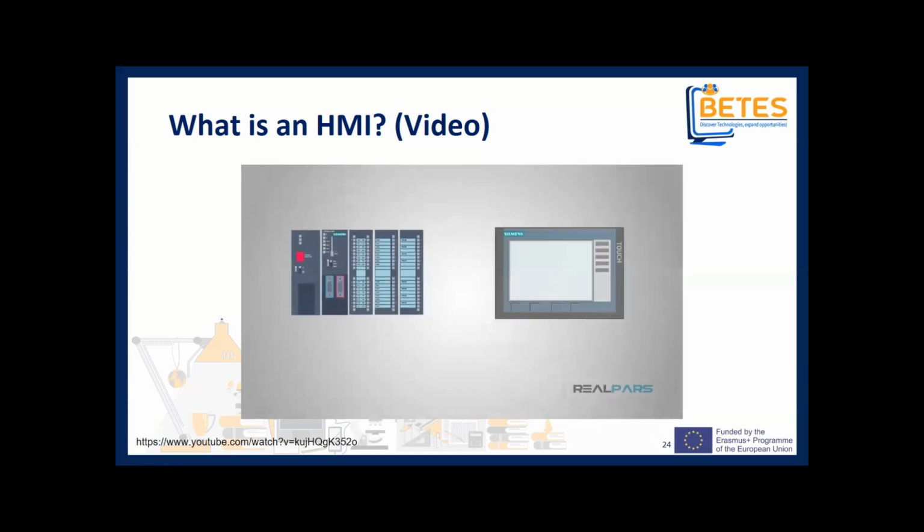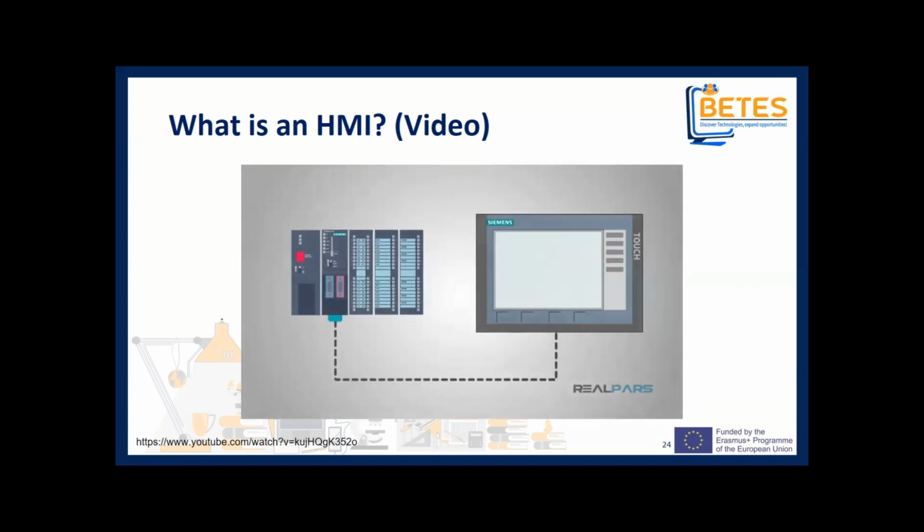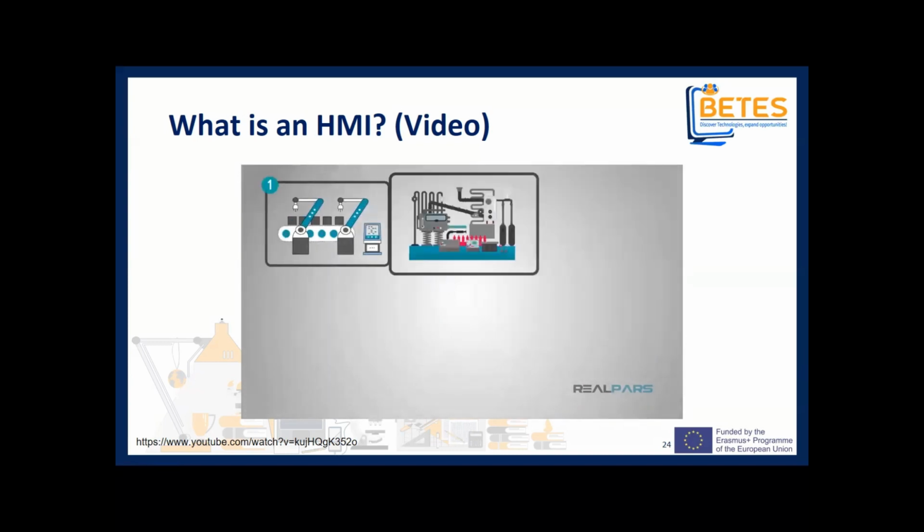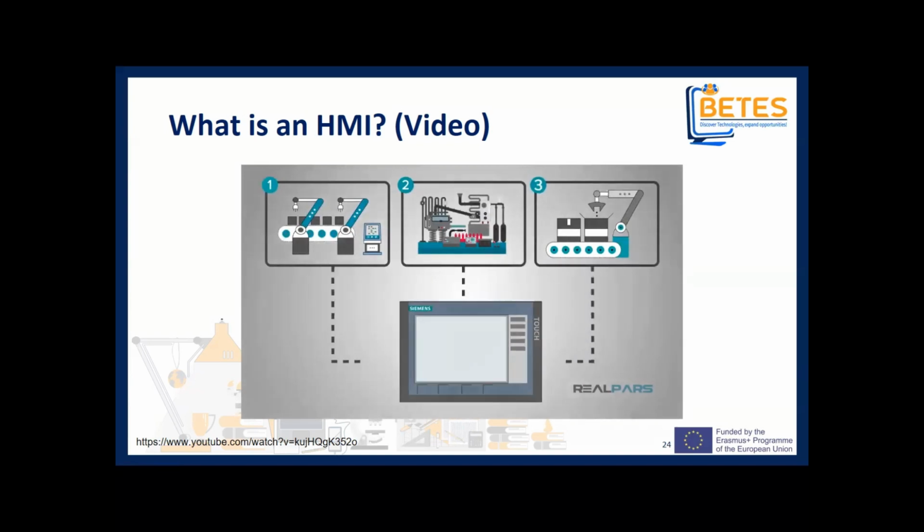For maintenance personnel, many HMIs can also connect to PLC logic and display it on the screen for troubleshooting purposes. This can save valuable time compared to connecting a computer or laptop every time. Another benefit of having a modern HMI is the fact that plants and other industrial sites can monitor and control multiple machines or other equipment.